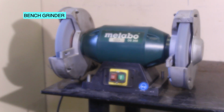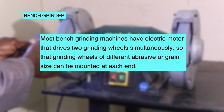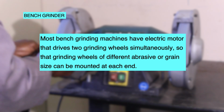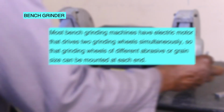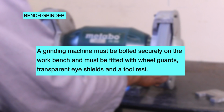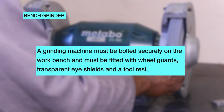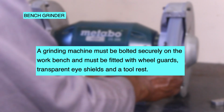Bench grinder. Most bench grinding machines have an electric motor that drives two grinding wheels simultaneously, so that grinding wheels of different abrasive or grain size can be mounted at each end. A grinding machine must be bolted securely on the workbench and must be fitted with wheel guards, transparent eye shields, and a tool rest.